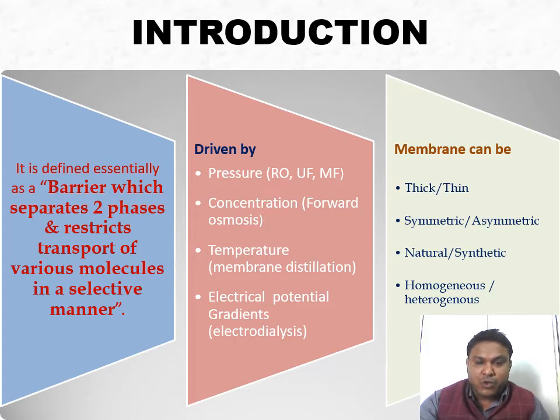Today, the most important use of conventional electrodialysis is the desalination of brackish water for the production of potable water. However, other applications are gaining increasing importance, including large-scale industrial installations in the food industry, whey and molasses demineralization, tartaric stabilization of wine, and de-acidification of fruit juices. But in this lecture, we will discuss pressure-driven processes only, especially focused on microfiltration, ultrafiltration, nanofiltration, and reverse osmosis.